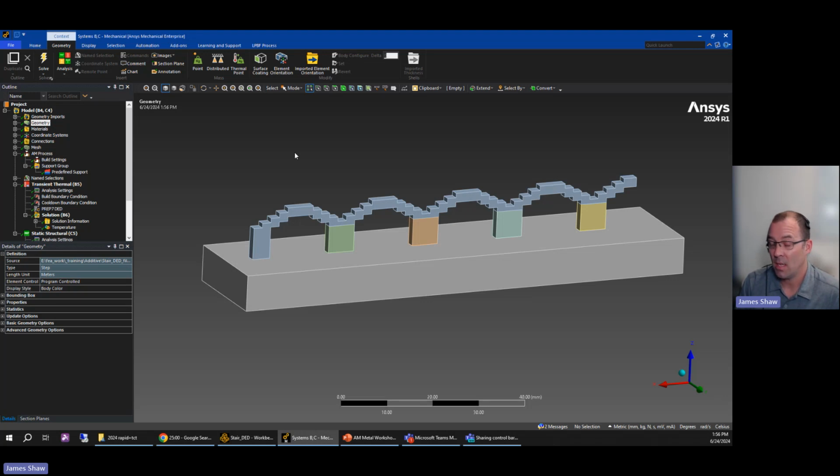A lot of times, and particularly in additive, what we're doing is building a model, making our best guesses, printing a part, finding out how close we are, and then tuning it. And so all of these models have a built-in tunability because it's so important. It's very rare to get the absolute first print out perfect. But certainly after a few prints, you can dial in this process, and then after that, you can predict it, and there's a lot less waste.